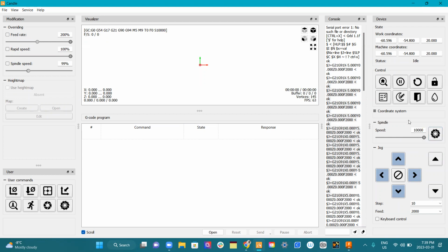If you are changing the drill bit on this, unplug everything. And I don't mean just turn it off, because if I turn this off, like I said, you're listening for a fan, and there is a slightly different light on the back, but it's barely, you can't probably even see. I'm turning it on and off here. And like with any machine, don't trust it, right? Unplug it, because while it is not very big and it is probably hard to hurt yourself, if you're holding on to it, it's still pretty powerful. I mean, it's still a machine.